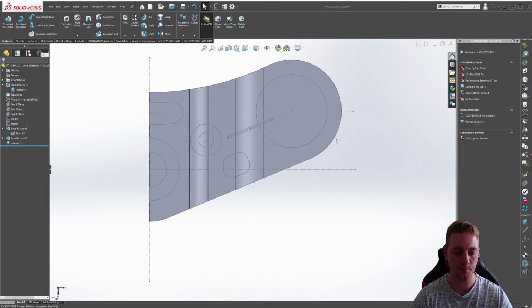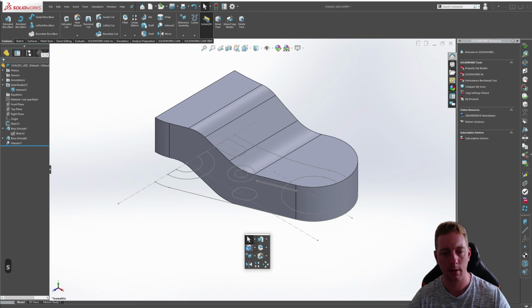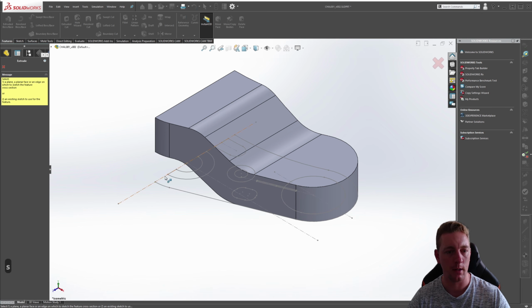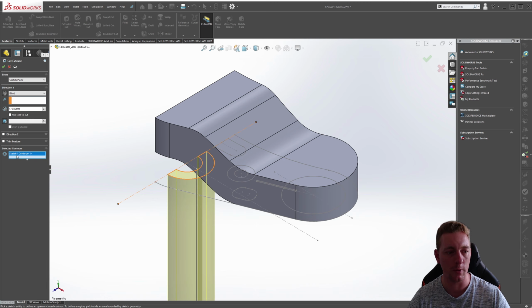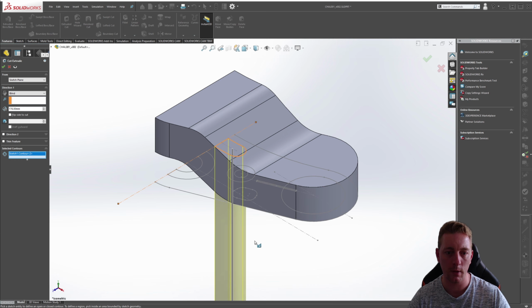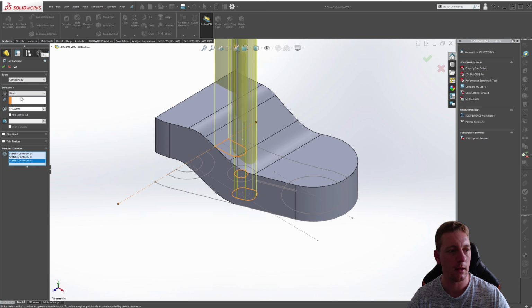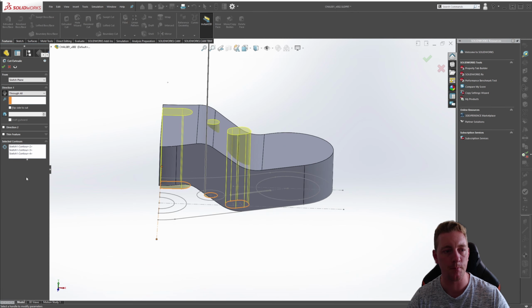Exit the sketch. Okay, now we can cut those bodies out. You can click on the sketch so it knows which one to use. We're going to select contours, clear it if there isn't anything, if there is something there we want. Actually, we don't want that one, so we can clear that. We want this one and this one, and we also want this hole because this hole goes straight through as well. You can reverse the direction, and you can just say up to surface and picking, not that one, so I might just say through hole. Through hole is probably the easiest way.